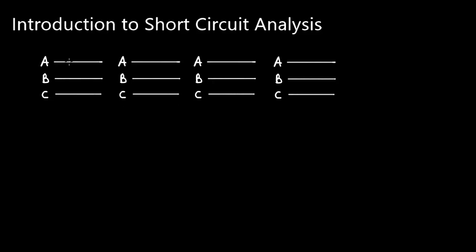The most severe one is often what's called a three-phase fault, where basically all three conductors get shorted together. They may be shorted or not to ground. That doesn't really matter for a three-phase fault, as we're going to explain in a future lecture. But basically we have all three phases, A, B, and C, shorted together, which is obviously not something that you want in a power system. Remember that the voltages across each conductor have the same magnitude, but are shifted by 120 degrees from each other. So if you short them out, it's essentially shorting out a voltage source, which causes a spike in current. This is what a three-phase short circuit would look like.